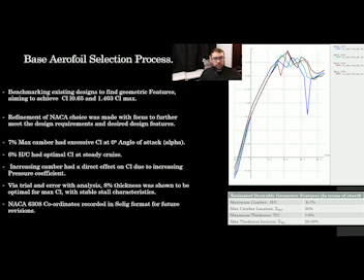9% thickness showed lower lift-to-drag ratios due to the higher profile drag. 8% thickness was optimal because 7% thickness had larger boundary layer separation when compared to 8%, causing lower CL max.